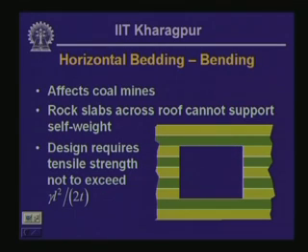So basically what is preferred in this particular case, and that is often adopted in design, is that a square cross section of the tunnel is often preferred, because if you have got a square cross section, then the slab near the tunnel crown, the roof of the tunnel, is not likely to lose any thickness, and as a result the stability is going to be much more if you have got a square cross sectional tunnel.